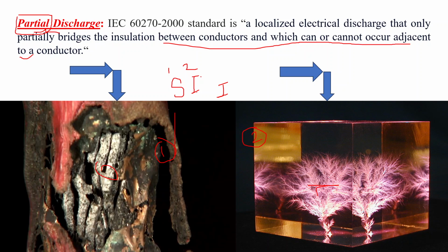Partial discharge can have several negative effects on the electrical system. It can cause progressive deterioration of the insulation, leading to reduced system reliability and potential breakdown. The discharge can generate localized heating, which can further degrade the insulation material and increase the risk of failures. In addition, partial discharge produces electromagnetic waves that can interfere with nearby electronic devices and communication systems.